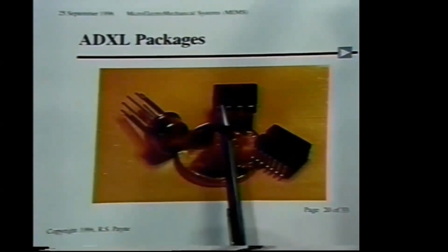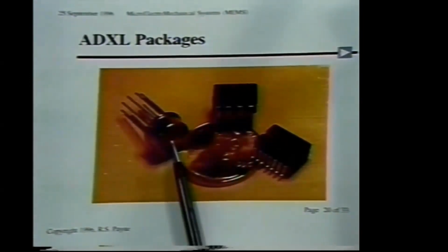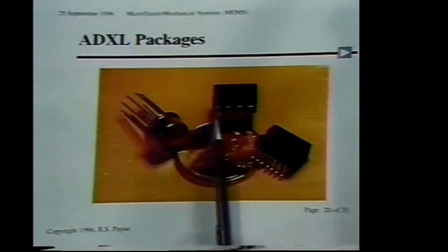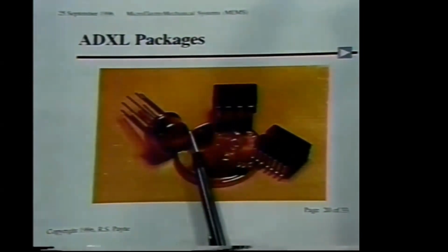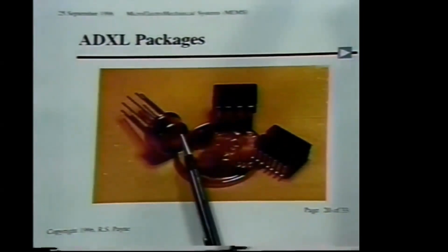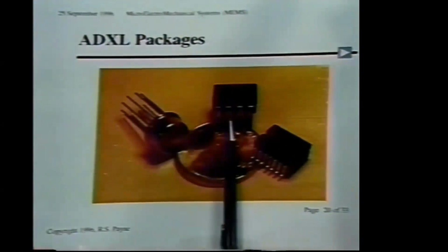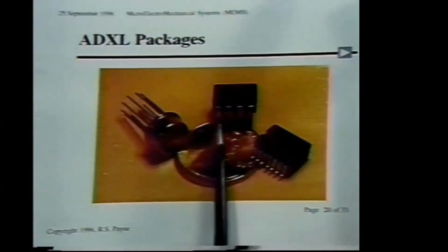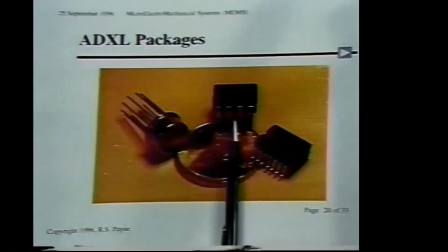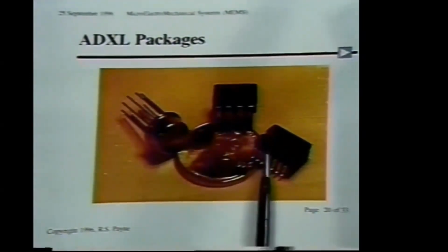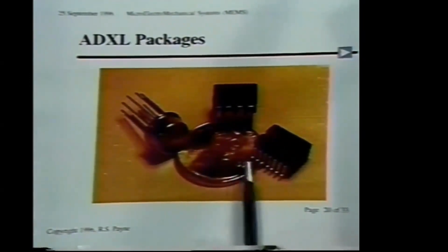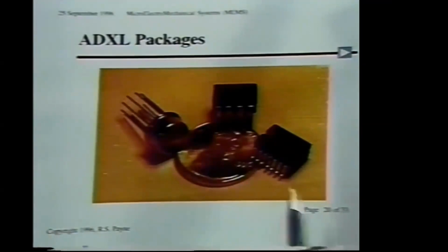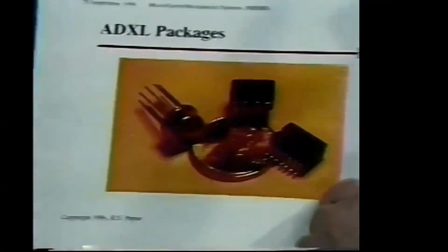But this device cannot be automatically assembled, again a feature that I'm sure many of the mechanical engineers in the audience can get involved in, in terms of integrated circuit automated assembly into PC boards. So DIP packages, in this case an 8-pin through-hole mounted DIP, and soon to come a 14-pin surface mount device, were used for the packages.